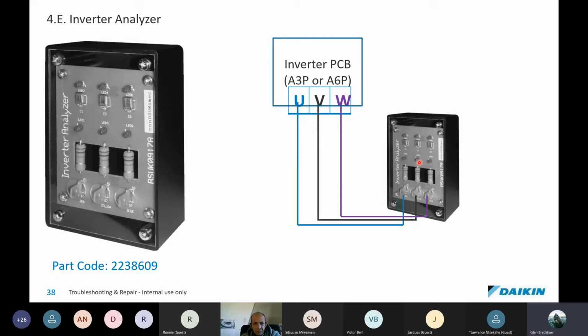As with all things, components fatigue, and although it gives a clear on the low output, when you put a load on it, sometimes that PC board is damaged. So just keep that in mind if you are working on VRV3 and you're getting L5 errors. Very often it may be because the PC board has actually reached the end and components have become fatigued on it.